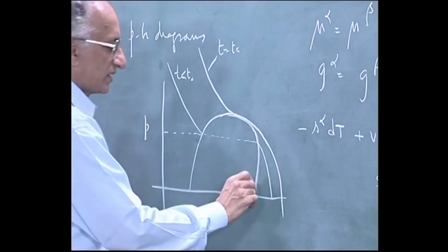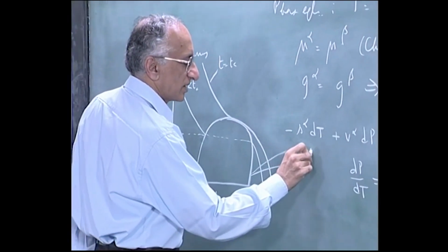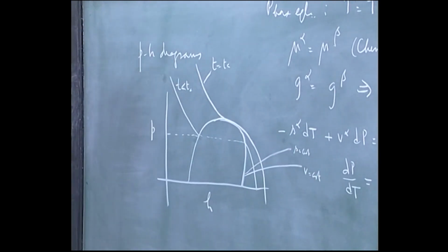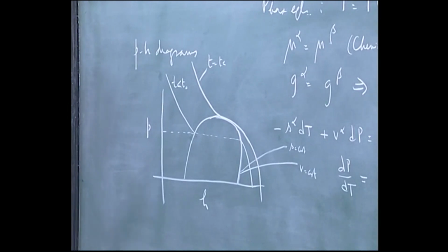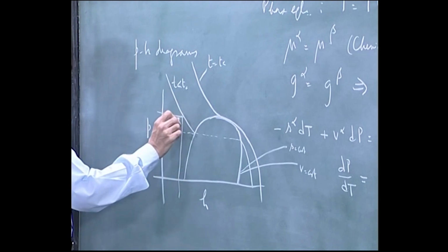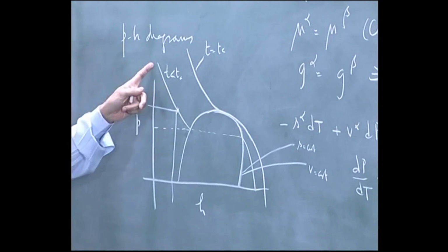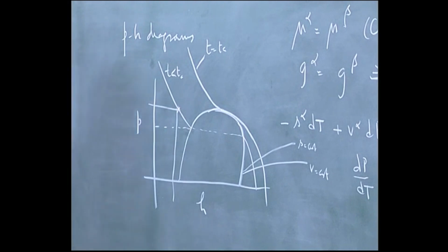So, in this region of course we have all the isentropic lines, this is S is equal to constant, this is V is equal to constant and so on. You can read any of the values. It takes two coordinates to fix the position of a state. For example, here any H and P will fix the position, then you can do it in terms of any two variables. If you fix the temperature and the pressure, this point is fixed. If you fix the temperature and enthalpy, this point is again fixed. So, any two variables will specify the state of the system.